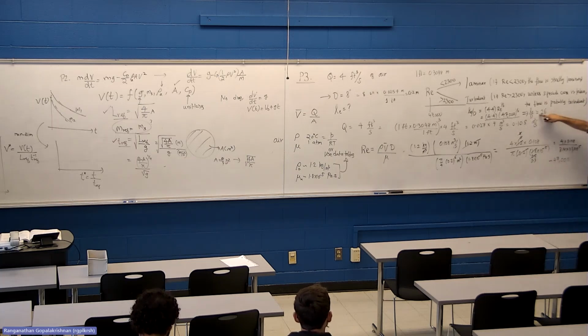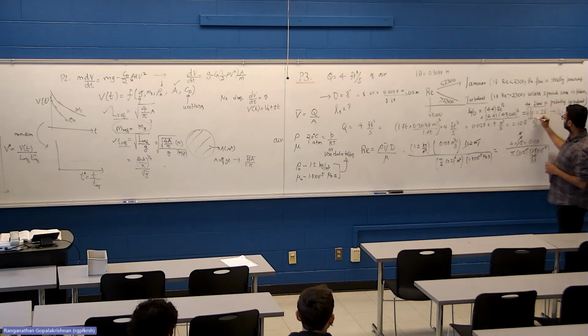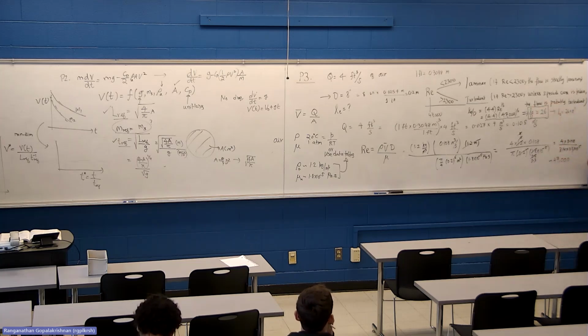So the simple interpretation of this statement is the entrance length is 26 diameters. If your diameter is 1 inch, it's 26 inches. Our diameter happens to be 8 inches, which means LE in inches is 26 times 8 inches. But it's not the actual number that is important. The number that's important is the entrance length as a multiple of the reference length, which is 26 diameters.